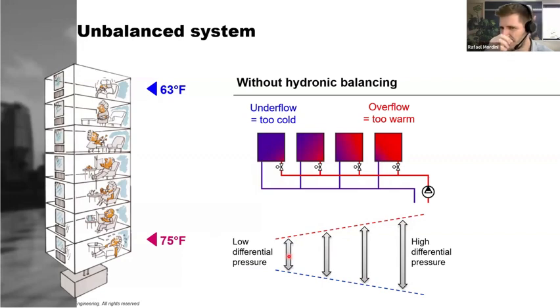This is how we can identify the index circuit, the most critical one, right? You just have to find the one with the lowest differential pressure. In this case here, this poor guy doesn't have enough. In some projects, you go to measure the flow rate and it has zero flow rate. It looks like your pump is not even on, but the pump is on, it's at 60 Hertz, right? The first equipments can tell.